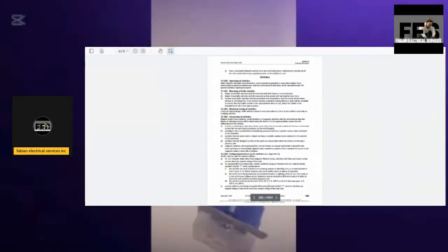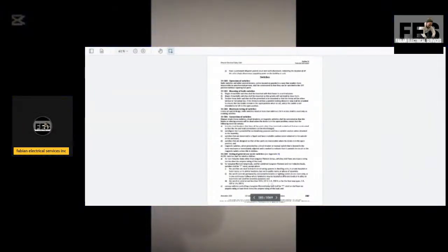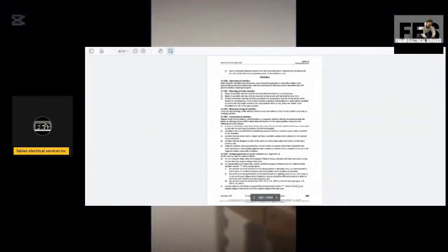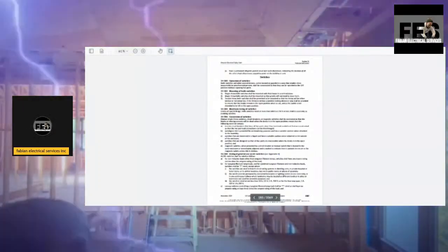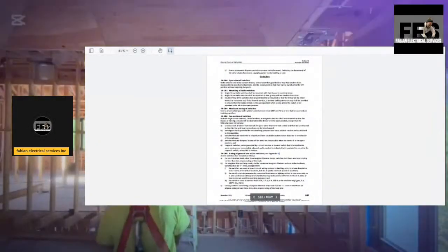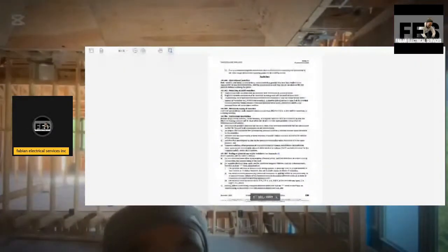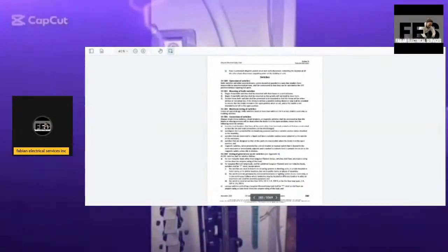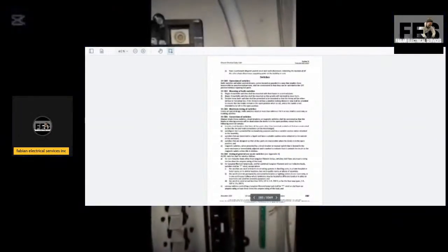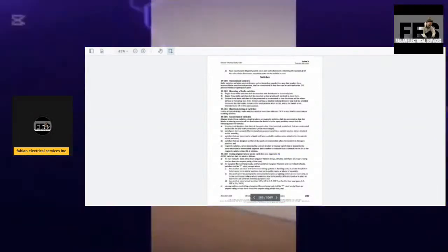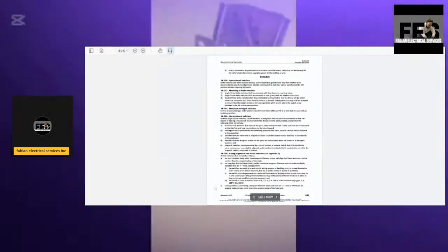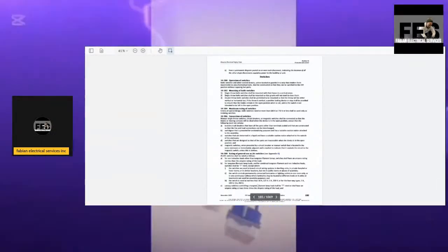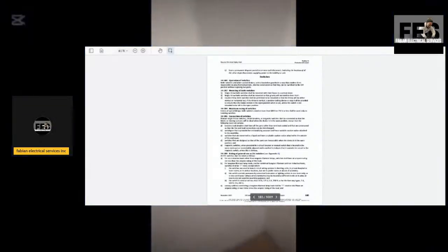than 10 amps, 125 volts, 5 amps, 250 volts, or for the four-way types, which you're going to see me using in the home where I'm working, it says 5 amps, 120 volts. Notice everything here is 125 volts. This is actually the lower single line that you're going to be using. So that means it's going to be one hot going in with a neutral, or you have 250 volts.